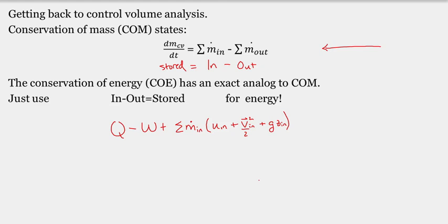And if we have potential for the mass to leave the system, we're going to have mass flow rate that has associated with it internal energy, kinetic energy, and potential energy. And I look at this equation, I say, hey, these are mass flow rates. So these terms are on a rate basis. So I better come back over here and correct my heat transfer and work transfer terms to make sure that they represent heat transfer rate and work transfer rates.